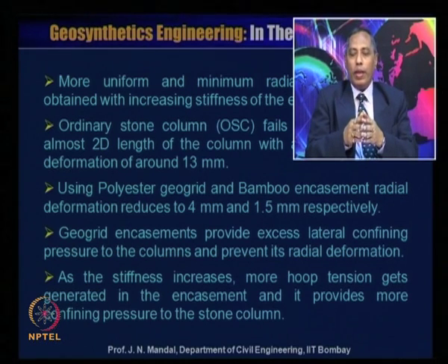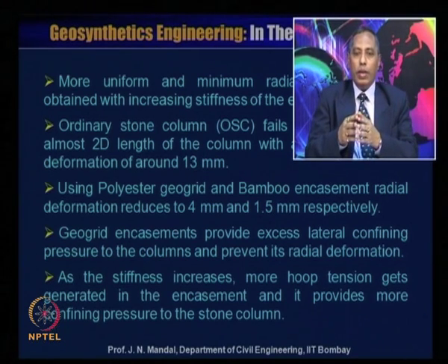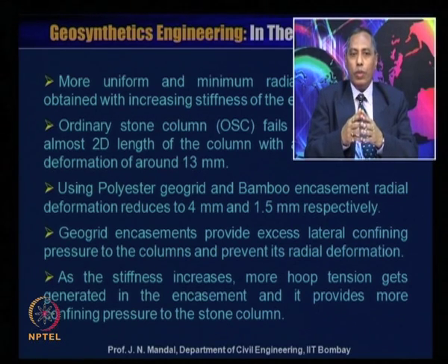Also, how a natural material like bamboo geogrid can be incorporated, and we find that its stiffness has increased and the radial deformation has been reduced with respect to the ordinary stone column. So, there is potential use of the bamboo geogrid as a reinforcement in India and some other parts of the world.